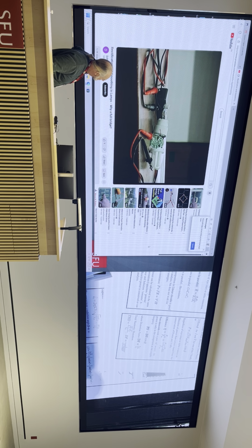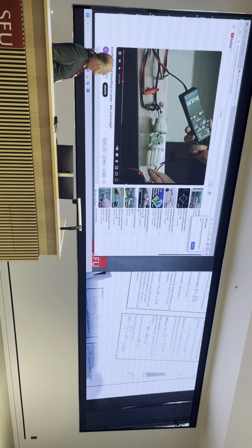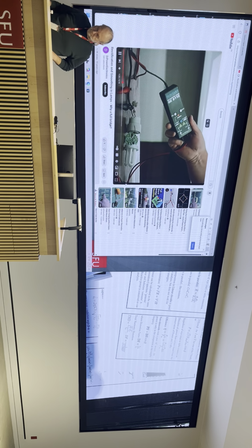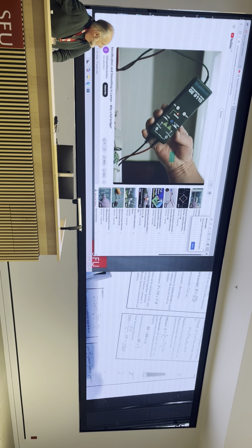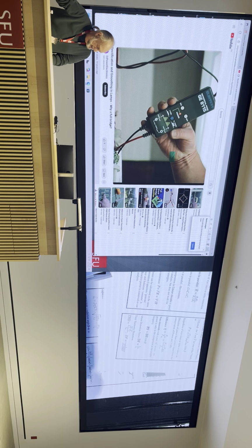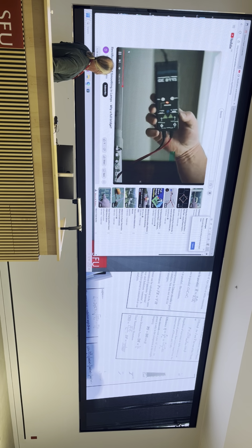Okay. Right, we're going to measure voltage. We're going to use these rather special differential probes. This is mains voltage. Don't do this at home, it's very dangerous. These differential probes are designed especially for this type of activity. So there's no earth, there's no ground, and you can just connect across.